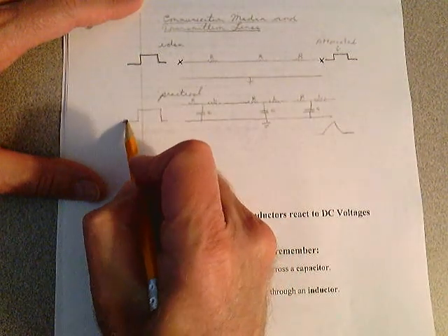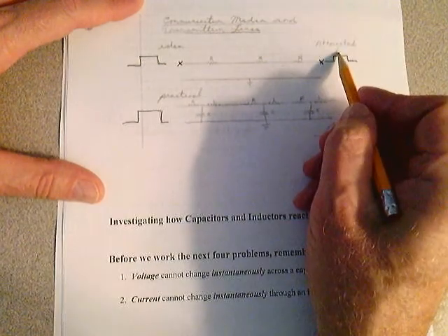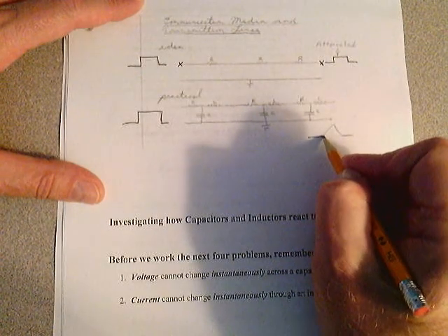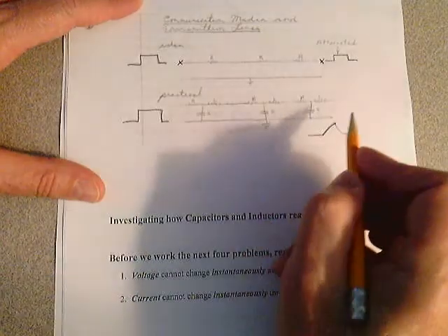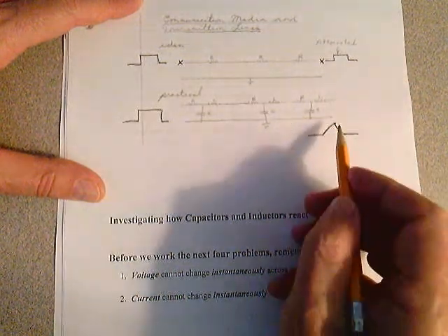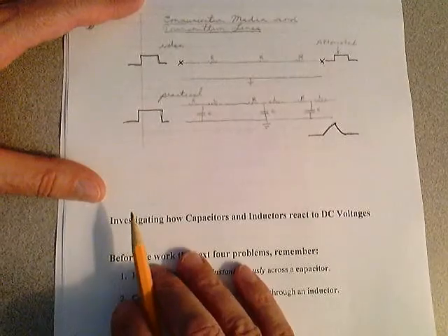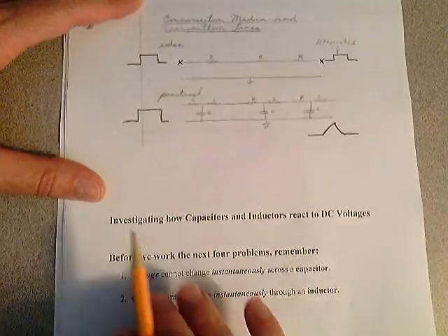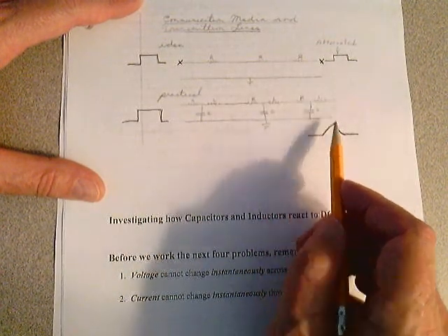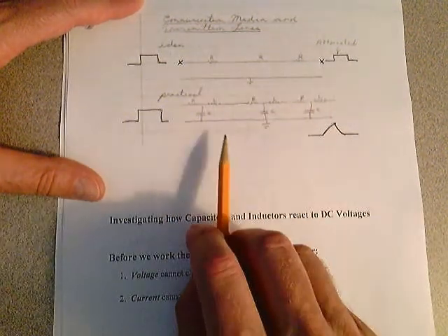Okay, so you'll not only get an attenuation in this signal at this other end due to a loss in voltage because of the resistance, you're also going to get an effect that gives you some roundness or some exponential shape to the pulse. That's due to the capacitance and the inductance in the circuit, or in this wire. At the higher frequencies, that capacitance and that inductance plays a significant role. At the low frequencies, pretty much ignore it.